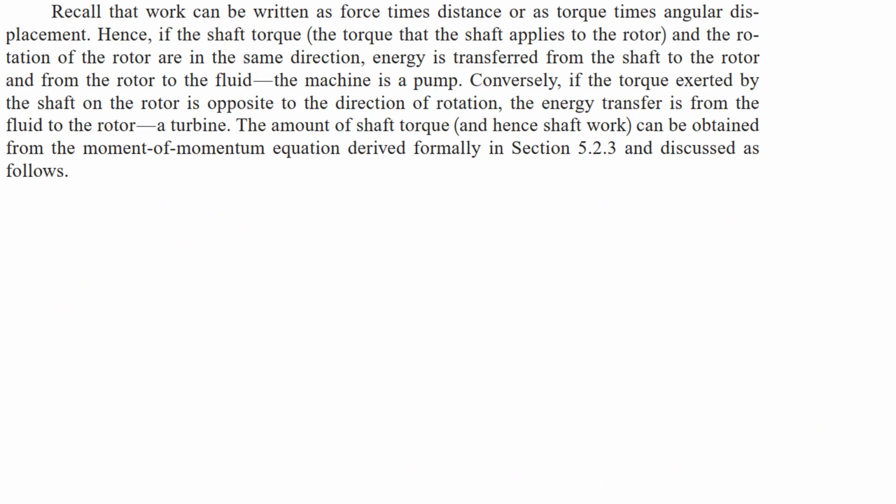So this is what we discussed in the previous slide, that if we recall, force times distance is work, or torque times the angular displacement. So work can be written as the force times distance or the torque times the angular displacement. So if the shaft torque, the torque that the shaft applies to the rotor, and the rotation of the shaft are in the same direction as we discussed previously, then the energy is transferred from the shaft to the rotor and from the rotor to the fluid, which is the scenario for the pump. So the machine is a pump.